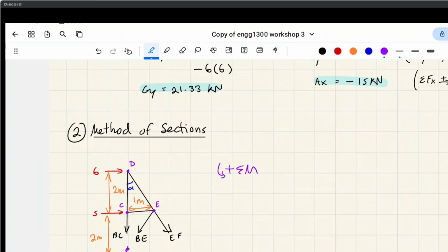In this case, if I take the moments about B and draw the unknown lines of action, we can solve for EF, because 2 of these unknowns intersect at point B. So you can always take a point off of the drawing. However, the question asks for BE, so we don't care about that.